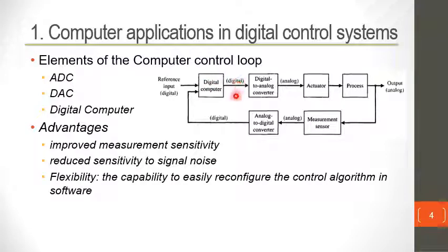This digital signal has to be converted to an analog signal because most of the process and actuators would be operating using analog signals. You can imagine here, for instance, the speed of a motor, which would be in the form of a digital signal spelled out by a computer in bits, and then the converter will convert it into a relevant, say for instance, a continuous voltage, which would be an analog signal.